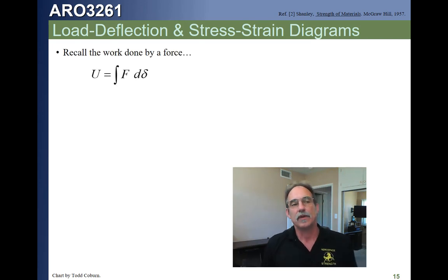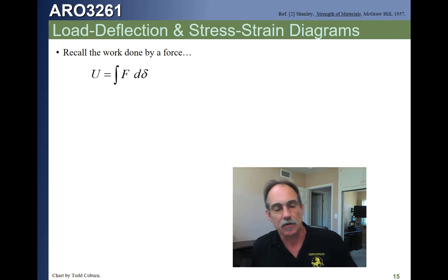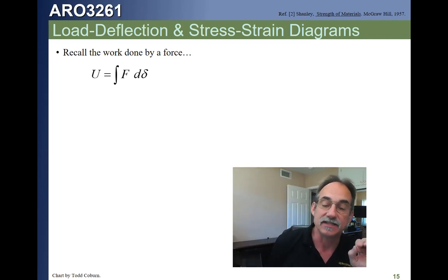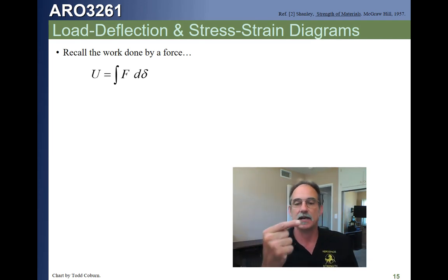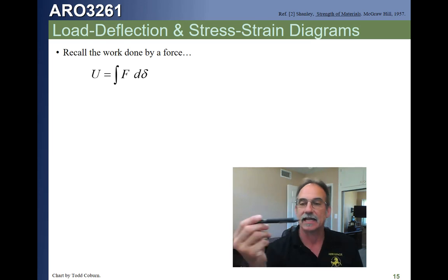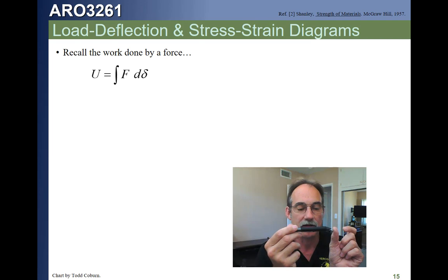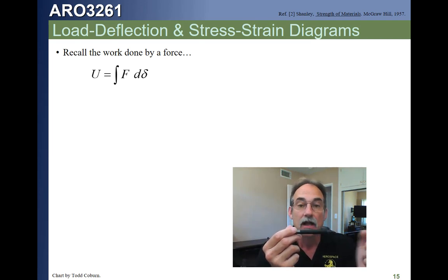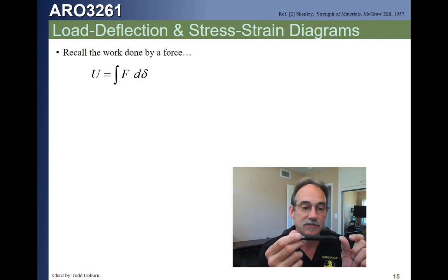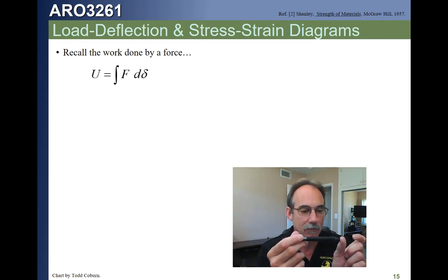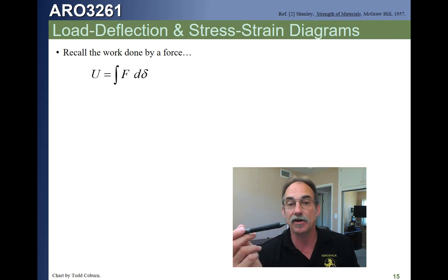So if we go back to energy, remember energy is just force times distance. Now if you take force, let's say we have a part, and let's say we pull on it in this direction. The energy is just the force times the distance, right? That's the work. If we pull on it this way and it moves that much, that's called work. We have a force and it caused a deflection. Force times deflection is energy.